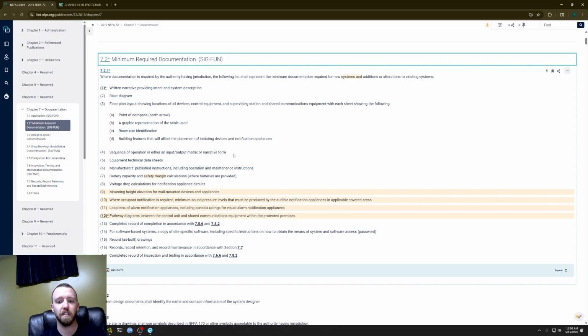You need wire charts that show and data sheets for those wires. If you have linear heat detectors, we need to see that. If you have flame detectors, any special systems, you need to indicate every single device and have the model so that the plan reviewer can review those devices, the equipment, the data sheets to what function that device is supposed to have, right? And make sure that it is compliant with the fire code and with this standard.